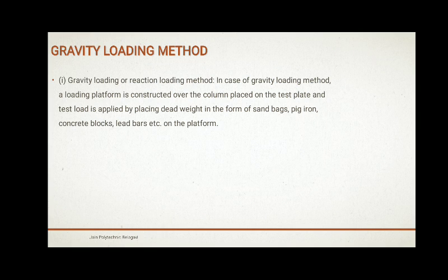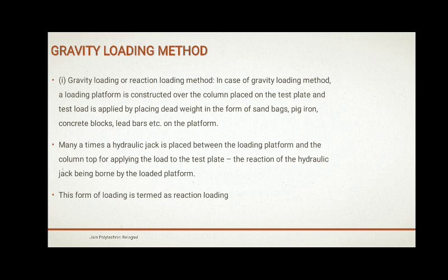In this case, a platform is constructed and loads are placed on the platform in the form of sandbags, pig iron, or concrete blocks. Many times a hydraulic jack is also placed between the loading platform and the column top for applying the load to the test plate, the reaction of the hydraulic jack being borne by the loaded platform. As I said, this method is also called reaction loading.